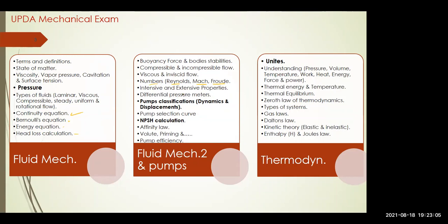Pressure meters. These are some types of devices for pressure measurement. This is all related to fluid mechanics. Then going to the other topic, which is pumps, and we study here all the information about pumps, like pump classification, dynamic and displacement, pump selection curve, net positive suction head calculation, affinity law, priming, pump efficiency, everything related to parallel pumps, series pumps, what's different, and so on.